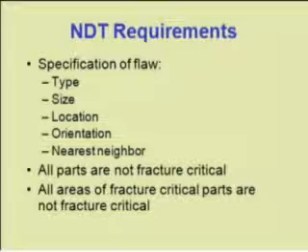And so inherently, the crack was put at the center point in the radius of a stiffened structure. In nature, that's not where the crack grows. The crack initiates and grows at the tangency point of that radius. So much of the work that had been done in lifing that particular engine had to be done over again because of an assumption that was not validated before we started the calculations.